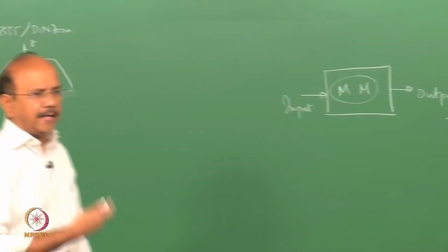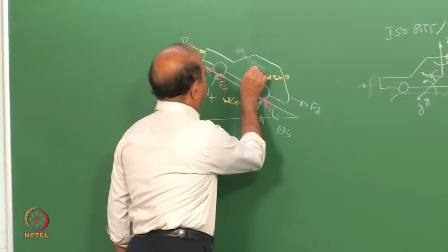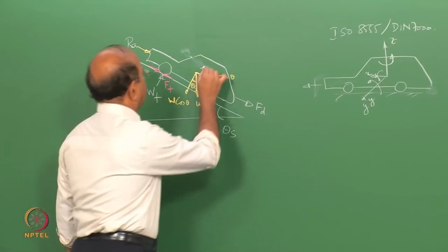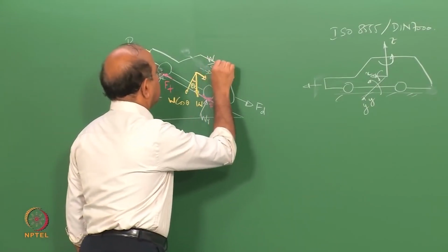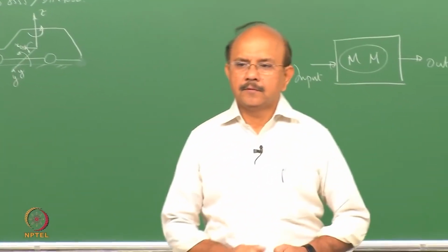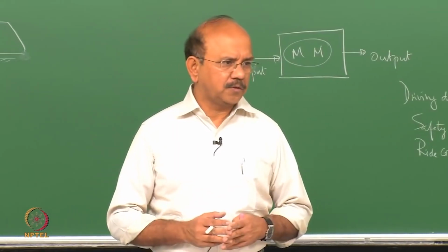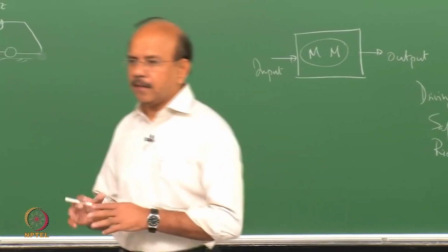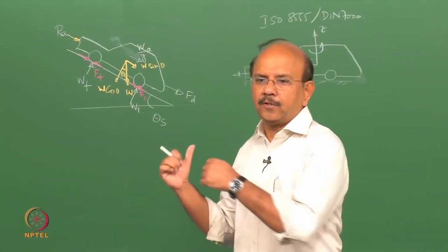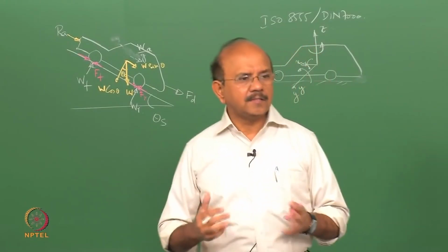Let us say that we are accelerating, of course we are applying a tractive force. So we can say that I have a D'Alembert's force, actually it is not a force, it is a pseudo force, which can be written as W by g into a. It is not a good practice actually to put this D'Alembert's force, it is nice to write F is equal to ma, but when I take some moments then it becomes easier for me to have a force there, and that is the reason why I have a force and call it the D'Alembert's force.